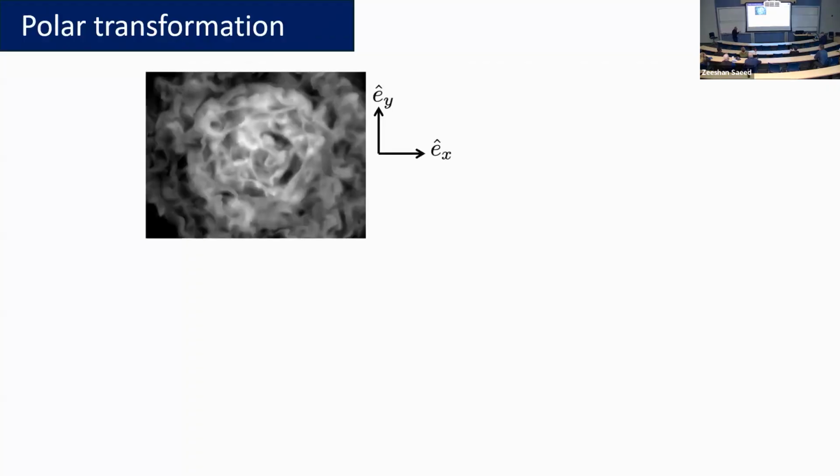As you may have also noticed, the flow is evolving as if it is more suited for a polar coordinate system. It is evolving in circles. The problem is there's a mismatch: my pixel distribution is Cartesian. I have my pixel locations, Cartesian coordinates mapping to where those pixels are, and the temperature value. That's problematic because the flow wants to be analyzed in polar coordinates and not in a Cartesian coordinate system, as one can appreciate from how the patterns are moving in real time.